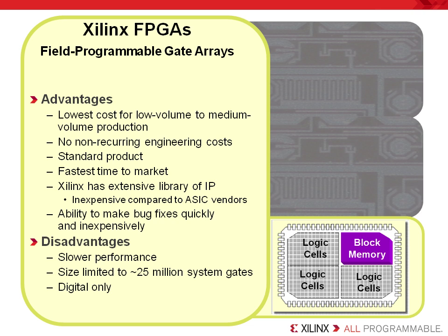Using Xilinx IP allows IP updates to be integrated into the design without the cost of a mask or a respin. This is helpful if you are using an emerging standard while the standard continues to be enhanced. This enables designers to adopt new standards early without the risk of a standard changing and then making your ASIC obsolete.